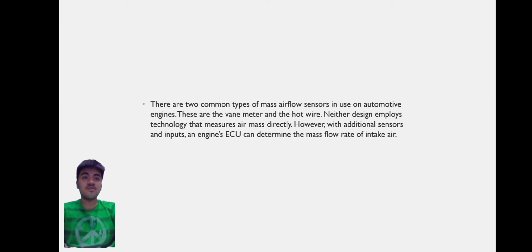Both sensor designs output a 0.0 to 5.0 volt or a pulse width modulation signal that is proportional to the air mass flow rate, and both sensors have an intake air temperature sensor incorporated into their housings for most post-onboard diagnostics vehicles. Vehicles prior to 1996 could have a MAF without an IAT. An example is the 1994 Infiniti Q45.